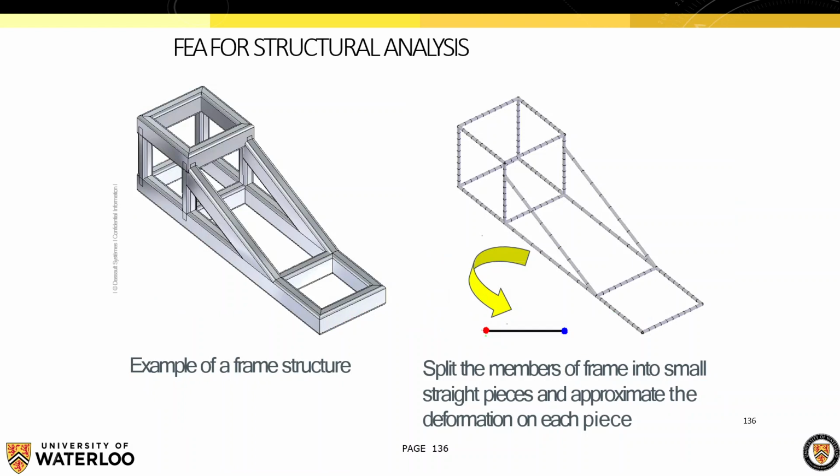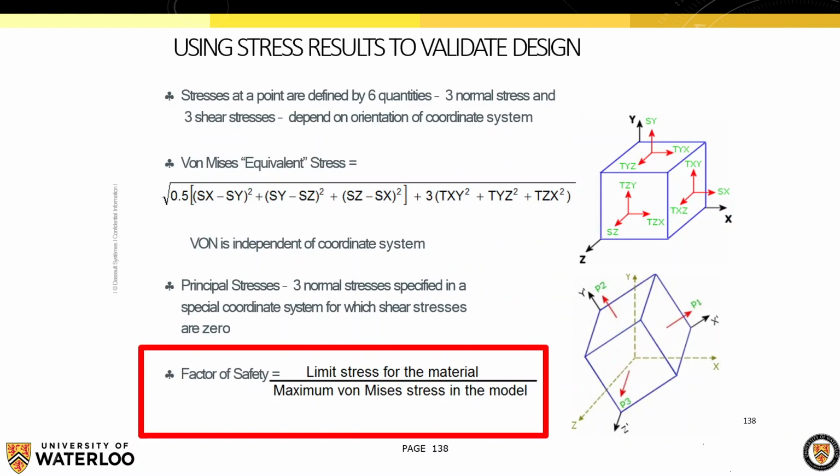Here's an example of a tubular structure that you might want to model using what are called beam elements. You can split all of these geometries into these beams, which are cylindrical kind of elements. In this case you can change the cross-sectional property to be cylindrical, box, C shape, whatever you want, but it's a different type of element that you can use for a different type of geometry.